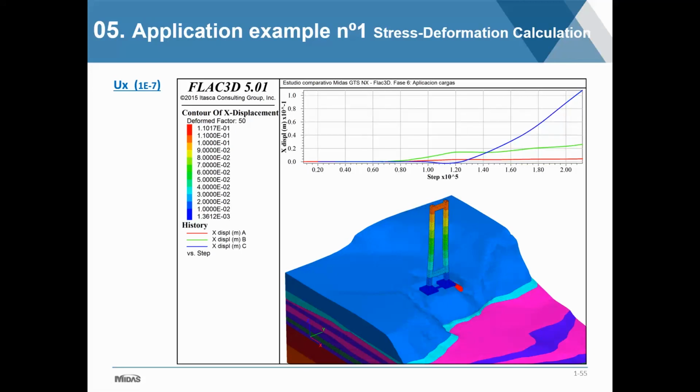We now look at the second criteria that we established, and we see that this is now starting to look more as we would expect. And we see now that it's the displacement at the top of the pier that's really starting to grow, and it's starting to get to a range that's more of what we had expected. In this case, it's still at around 11 centimeters. But it seems to still be growing.